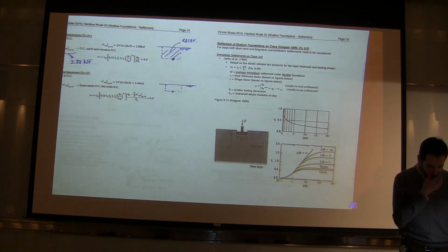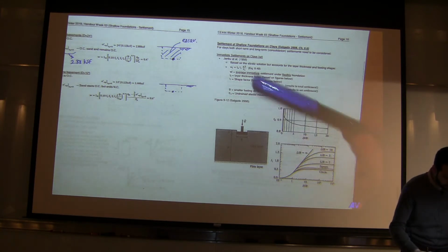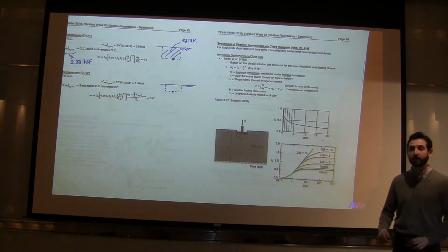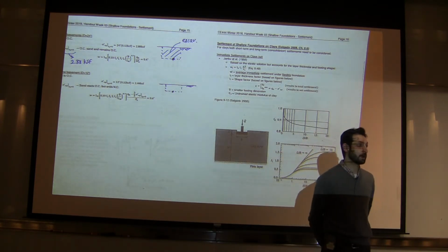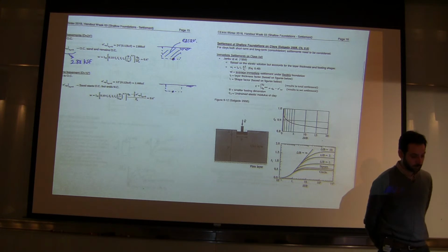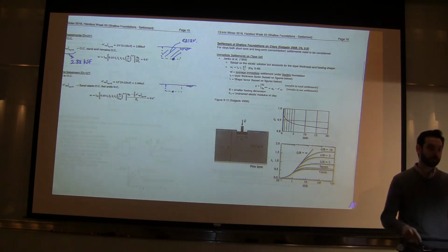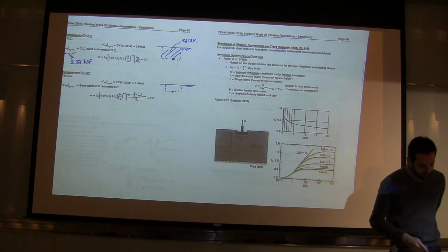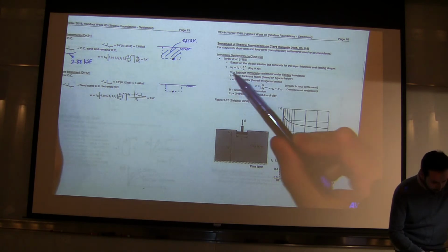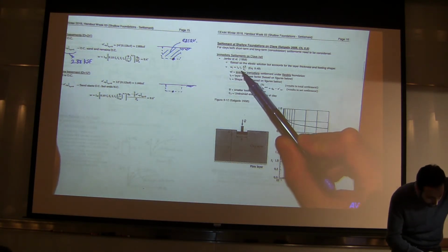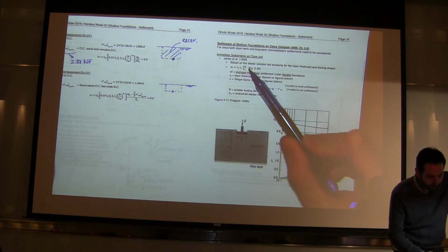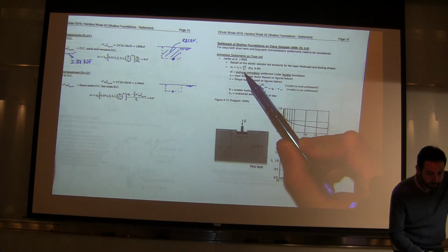clays. And it starts with the Janbu et al. 1956 equation. This is one of the very common equations that we use in practice for settlements in general, and specifically immediate settlements in clay. And let's look at the equation. W equals I0 times I1, multiplied by q times B divided by E sub u.